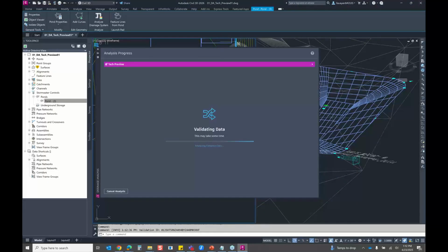So if it does find any errors, you can pretty much zoom to them or read them to see what's going on. This is brand new technology, so it's going to be a lot of new verbiage that you're perhaps not used to seeing. And as it runs this analysis, again, I just didn't give it really good values. I just popped in catchments, and areas, and hours, and minutes, and quantity. And my rainfall data may not be really accurate here, so it may take a little bit longer to run through this. It is using cloud-based computing to be able to run this.